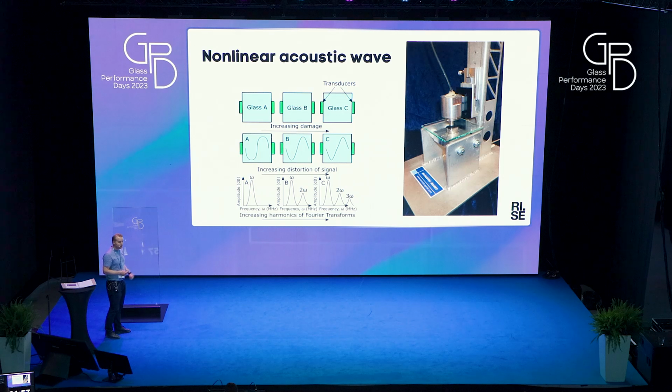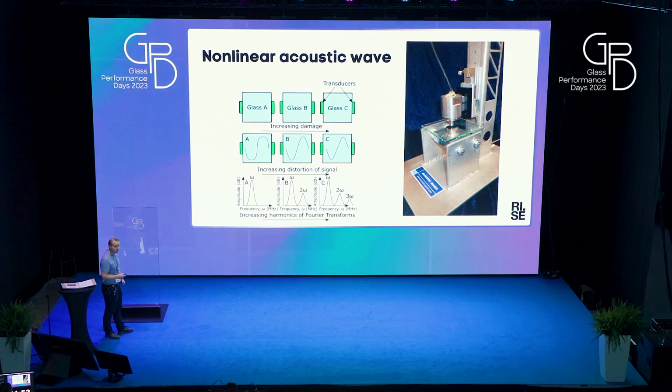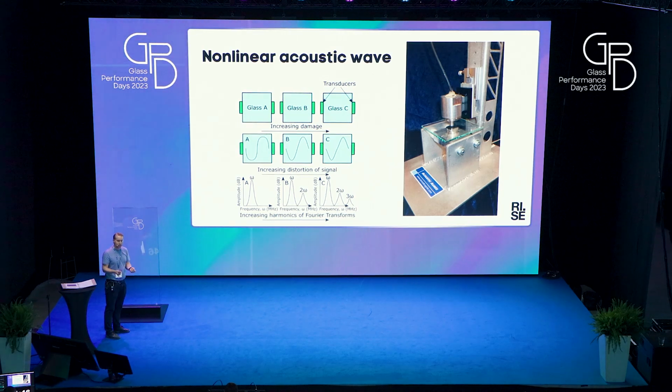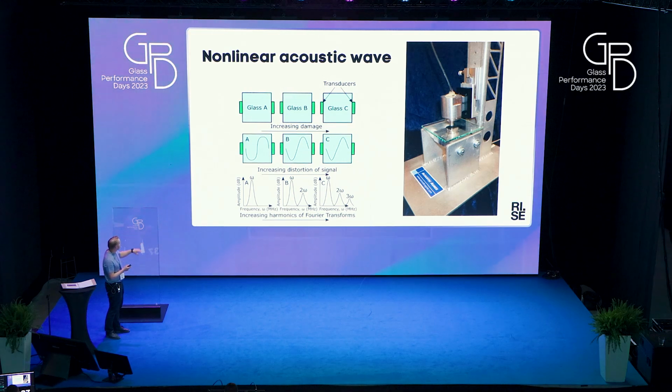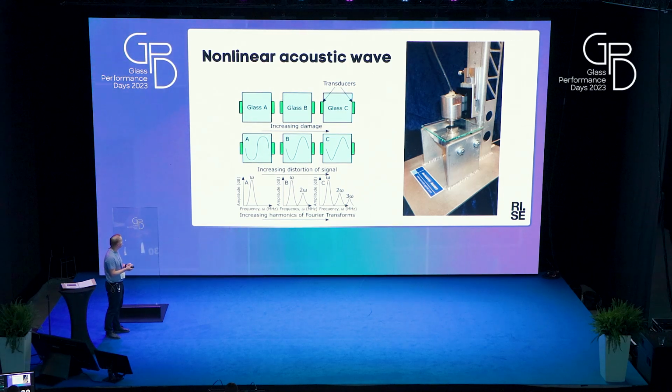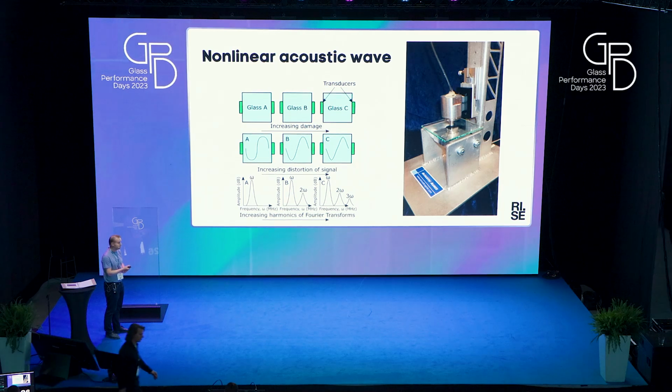And then about this non-destructive testing, we have used non-linear acoustic wave methodology, where, when you are tapping on a material, you can actually hear if there are any defects in the material. And here we are using ultrasonics, and if there are any distortions, defects in the material, there will be some distortion of the sound.